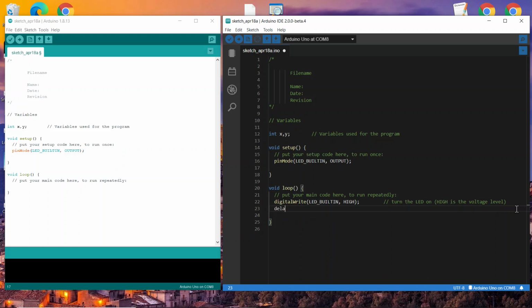And then I want to delay for a certain amount of time. So I start to type this in, and it doesn't look like it's gonna do the thing for me. But we know that you can delay a certain amount of milliseconds. I want to delay a second, so that's 1,000 milliseconds, and we sort of know that. So I'm going to hit the tab key a number of times to get me over here to keep all my comments lined up, and I'm going to have an end of line comment. I'm just going to say wait for a second here.